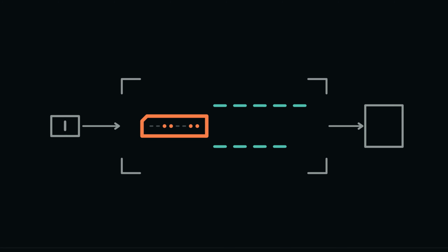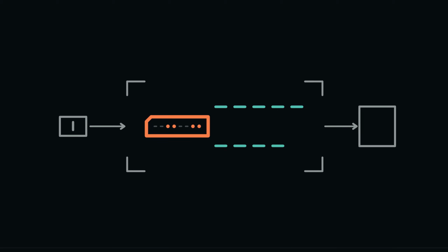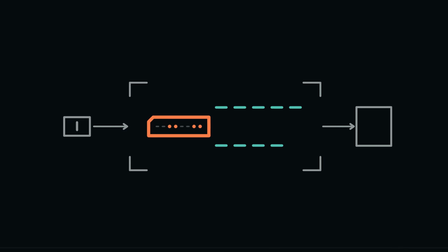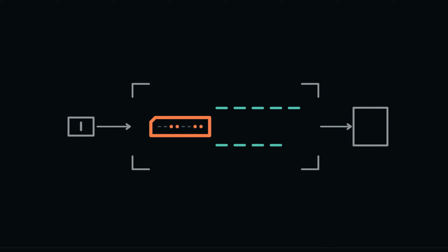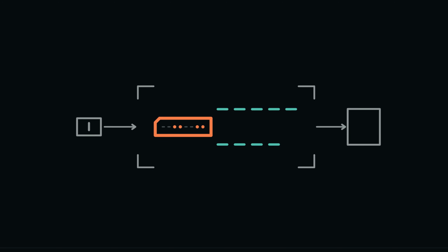A processor cannot begin by asking the system software what to do because no operating system instruction is running yet. It begins from a hardware reset contract. In SE8, reset clears the CPU registers and flags, selects a declared program origin for the program counter, and puts the controller into its first fetch state. Reset does not erase or initialize RAM. A contemporary processor has a different and far more detailed reset contract, but it still requires a defined place and mode from which instruction execution can begin.